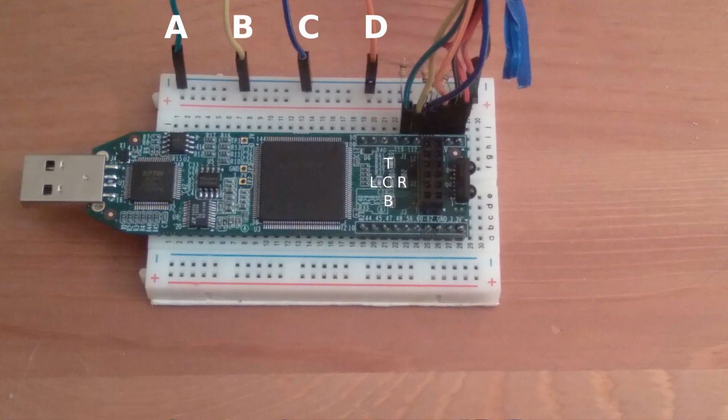This poses an issue, however. For whatever reason, if an I/O pin is left unconstrained, it is left floating. For these 5 LEDs, that means they'll glow faintly if they're not in use. So when you see them glowing when they're not supposed to, it's not your computer and it's not my camera. It's just a minor annoyance that I haven't researched how to fix.